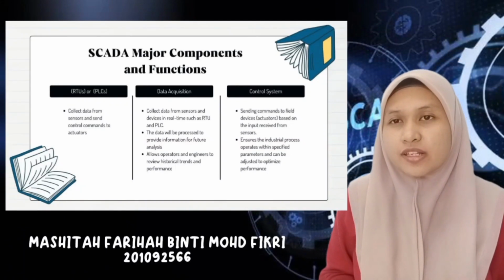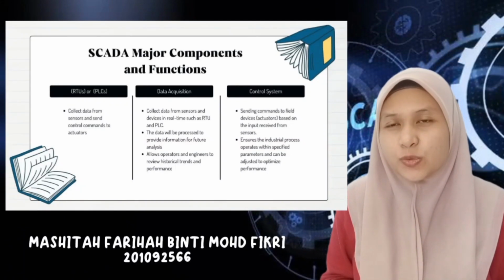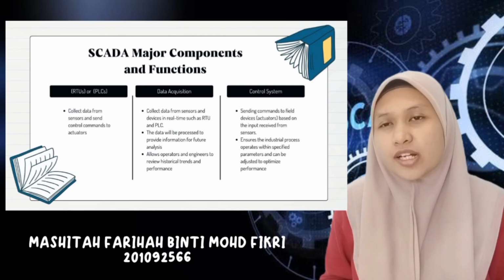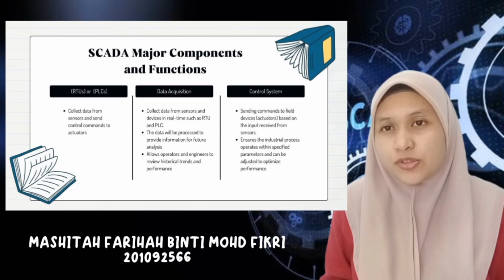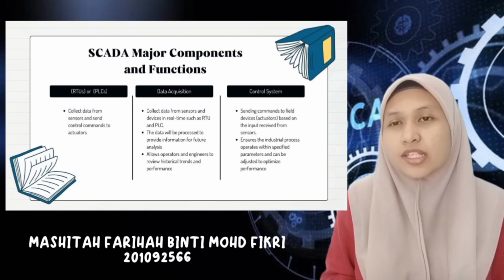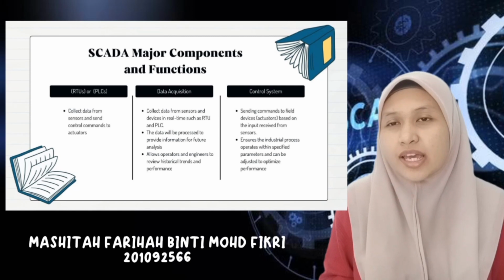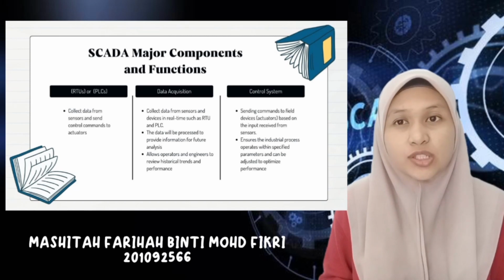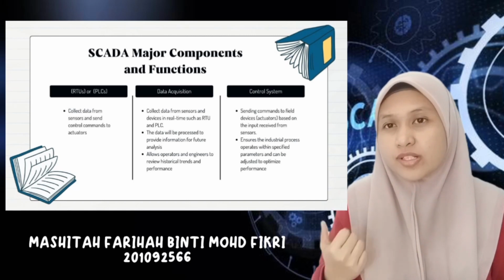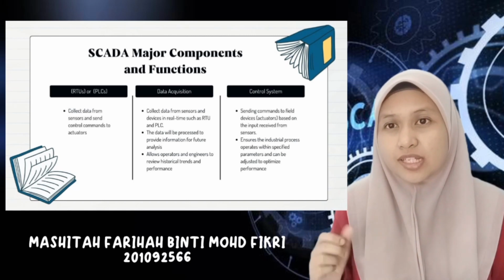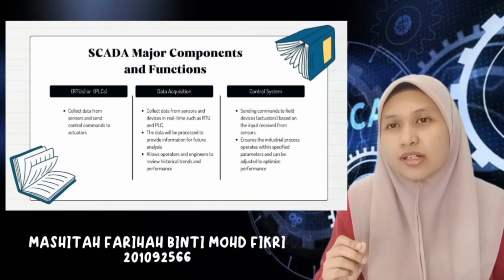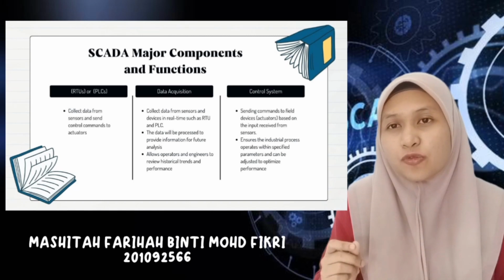So these are the SCADA major components and functions, which are the three types of components that we usually use. The first one is the RTU or PLC, the data acquisition and control system. The RTU and PLC collect the data from the sensor and send the control commands to the actuator. For the data acquisition, the data that we retrieve previously from the RTU and PLC will be processed to provide information for future analysis.